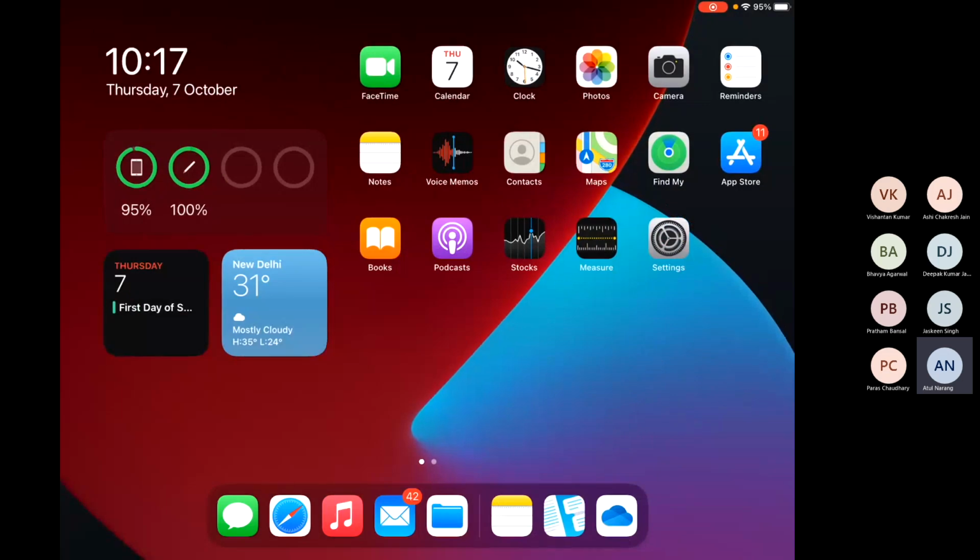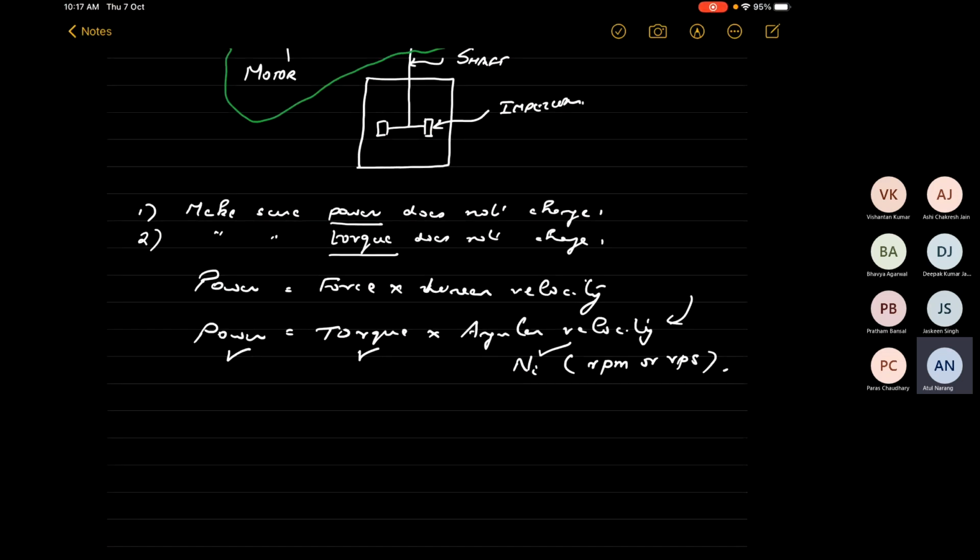Similar things happen in oxygen transfer. If oxygen is being transferred not by bubbling air through the system, but only through the surface, you have major problems when you scale up, because oxygen transfer is taking place across the surface, but it's being consumed in the bulk of the volume. So as you increase the scale, due to the decline in the surface to volume ratio, the transfer of oxygen into the system doesn't increase as fast as the rate at which it is being consumed.